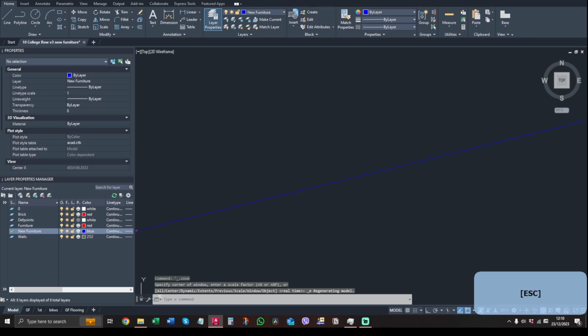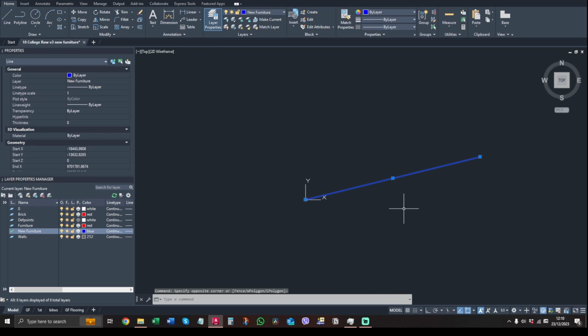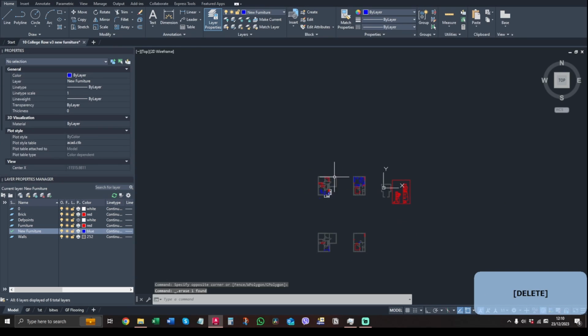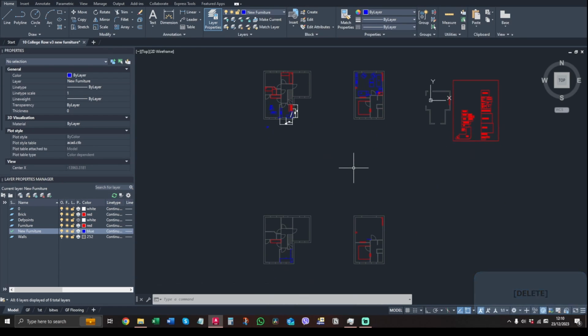Now if I do the double click thing, that's an enormous line, it's absolutely ridiculous. And what you'll find is that should actually solve your issue of not being able to zoom out. If that doesn't work, what you could try is regenerating. This actually solves a multitude of sins, but you can do regen and regen all, and regen all is obviously the better one, and it just makes AutoCAD stop and redraw everything.